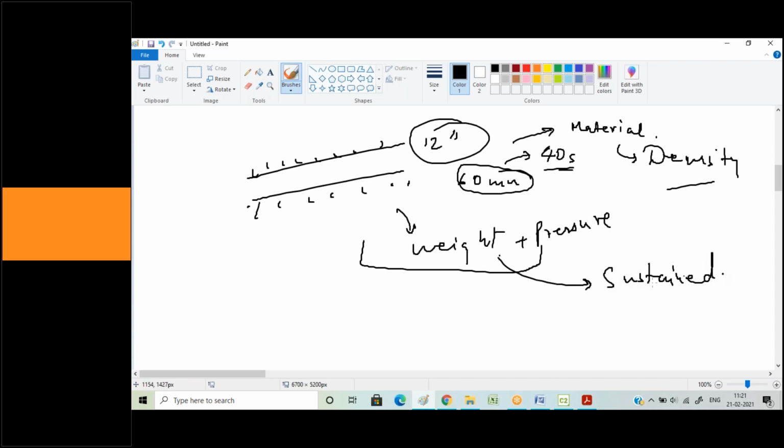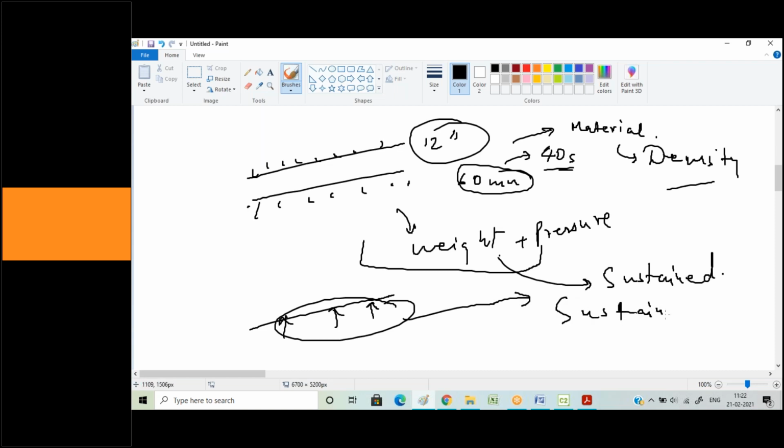So now, when I was talking earlier that when a particular engineer, say a pipe support engineer, or might be a pipe design engineer, is installing the supports, when he's saying I got to use this n number of supports in my pipe, what he's actually looking at is this criteria, sustained. This is the amount of support that I require in order to clear my pipe in case of sustained load.